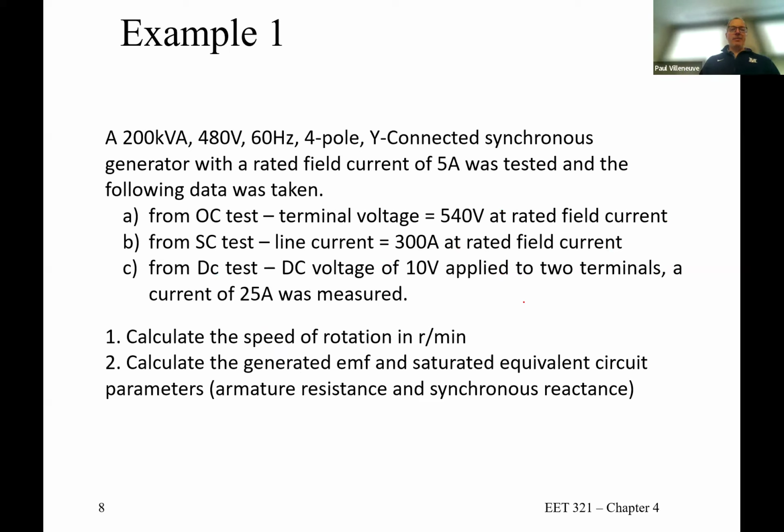All right, let's take a look at an example. 200 kVA, 480 volts, 60 hertz, 4-pole machine, Y connected. So that's important. Why is Y connected important? It's important for two reasons. The first thing is it gives us our diagram, which is going to allow us to see that this 480 volts is across two phases. The actual voltage, see if I can erase that.